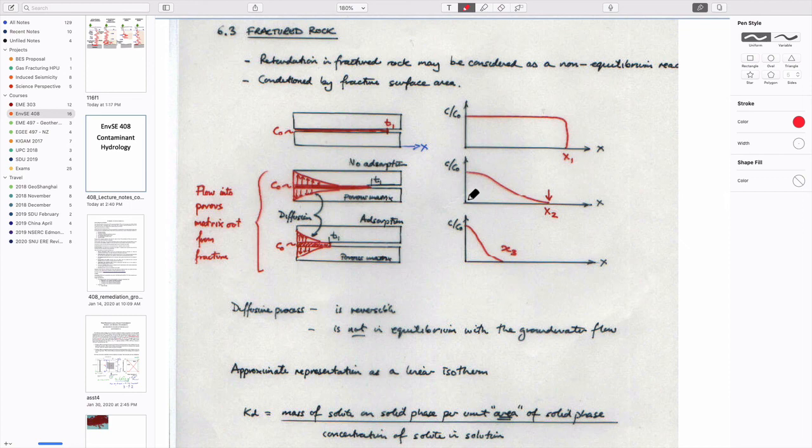But we made the case that when we're talking about flow downstream in a fractured medium, there are two effects. There's diffusion, which is molecular spreading by Fick's law, Brownian motion, and also these tortuous flow paths, which spread out the front from being a concentrated blob into something that's much wider. And so for flow within fractured rocks, you get a retarded plume that hasn't gone as far as it should have in a given amount of time. And in this case, actually, it's not sharpened, it's maybe softened, and can occur for other reasons.